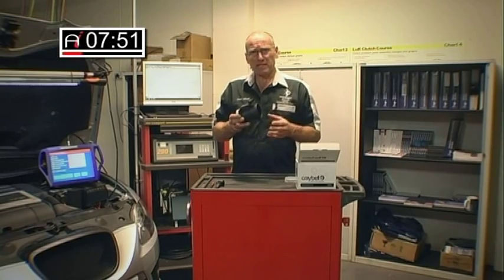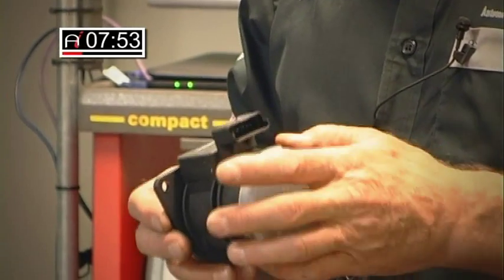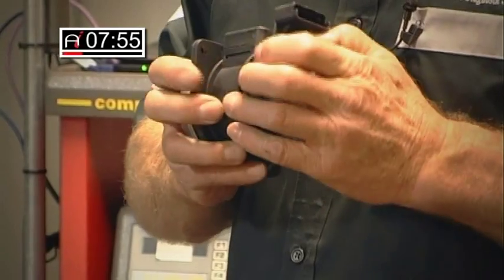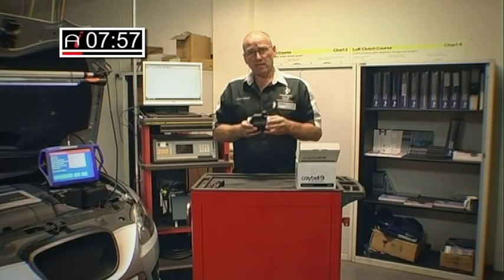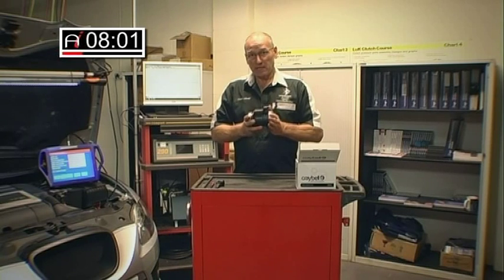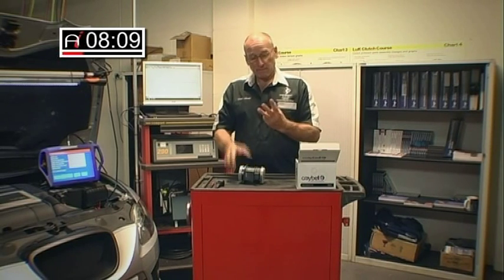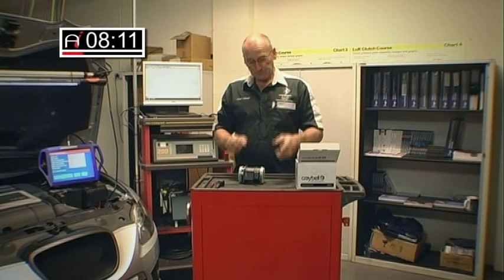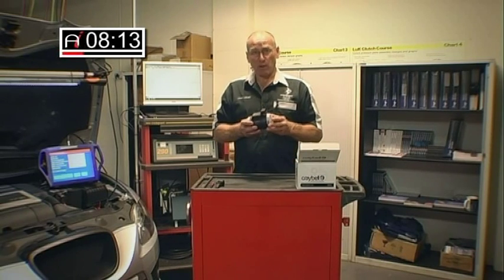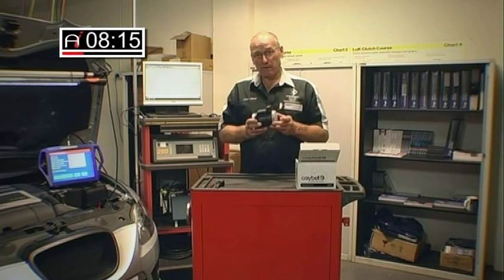So there are many reasons why these actually fail. So try and take those into account before actually blaming the air mass meter, and please try to remember that any sensor, and this is a sensor, requires power and ground to be correct before the output value will be correct. So the golden rule always is output, power, ground. Never reject an output value without first checking power and ground.